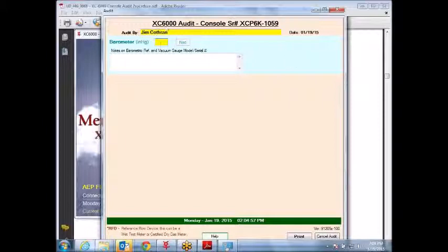Now, if we actually have a barometric pressure and just read it right at the port that we're on. Yeah, if you've got something to read it right there, that's fine too. Like I said, maybe in your control center, but that's probably at the base of the stack, so you're going to be up higher where the console is. Yeah, we have a correction factor on it. Okay, yeah, all we're doing is looking for the pressure.